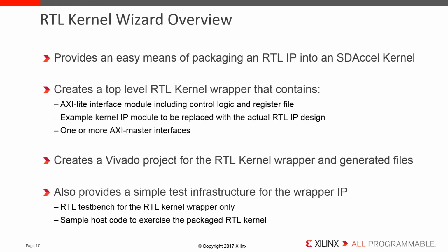The wizard automatically generates the AXI-Lite interface module, including the control logic and register file. The AXI-Lite interface module is included in the generated top-level RTL kernel wrapper. The wrapper also includes an example kernel IP module, which should be replaced by your RTL IP design.